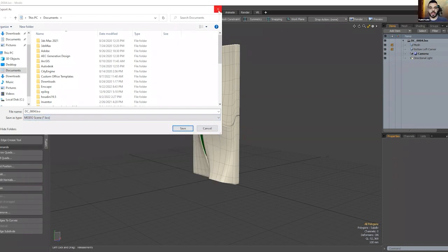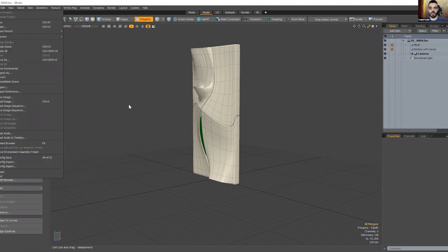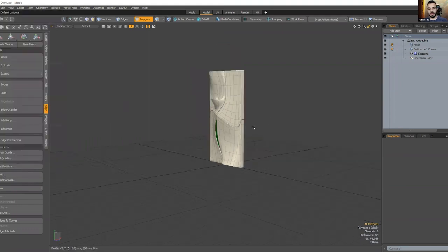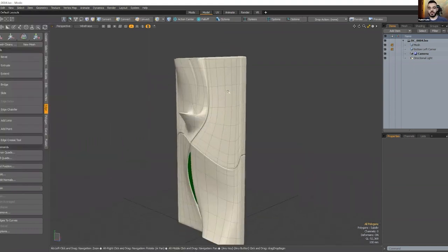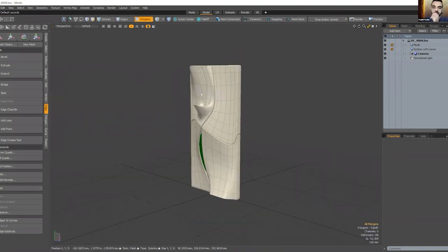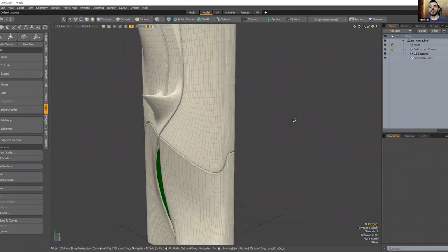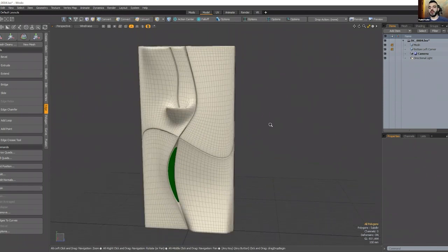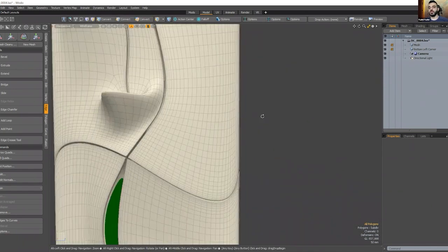So thank you. Yeah, so that's the export. It's simply, as I was saying, just in case I did it fast, File, Export, and that's how you export the object. One thing before you export this object, so that you don't lose the quality of it: if you go to Rhino SubD, you can certainly export it the way it is. If you're going to Rhino NURBS surface, then the resolution of it might be lost. So you might just have to subdivide it a couple of times, or a little bit more, so that you have more polygons and you don't lose the resolution of it.